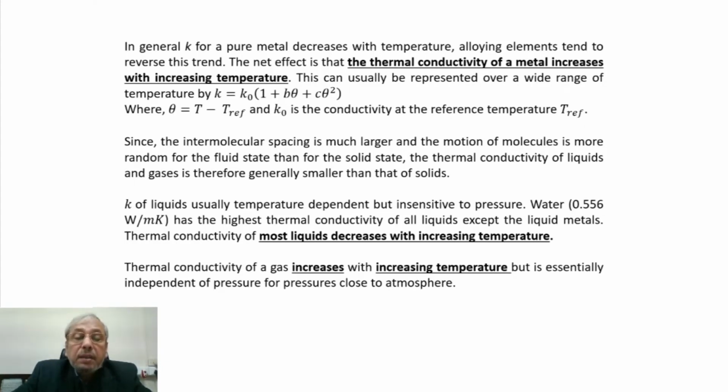Usually the working liquids are water or some alkaline, some acidic solutions or some chemicals. But for water, the thermal conductivity here we have written as 0.556 watt per meter Kelvin, which, as I mentioned earlier, is around 0.6 watt per meter Kelvin. It's a function of temperature. Water has the highest thermal conductivity of all liquids except the liquid metals. Thermal conductivity of most liquids decreases with increasing temperature.